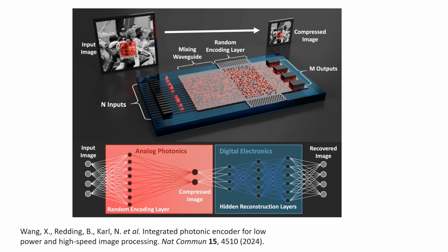Okay, so now we've got this compression, and we need to figure out how we're going to use this compressed data to recover the image. We would evaluate our H matrix based on, first of all, we'd like to make it unitary so that we have orthogonal rows in H if possible, so that we would have a flat singular value spectrum, and then we'd like the singular vectors to have a general structure that is consistent with measuring the object features that we've got. Now, this is the heart of computational imaging. We don't have pixels, we have coded data. We need to turn that into images again.